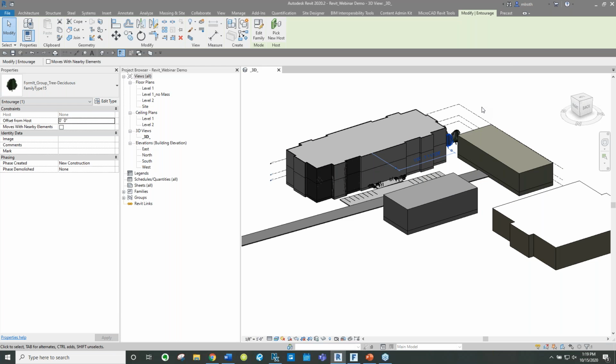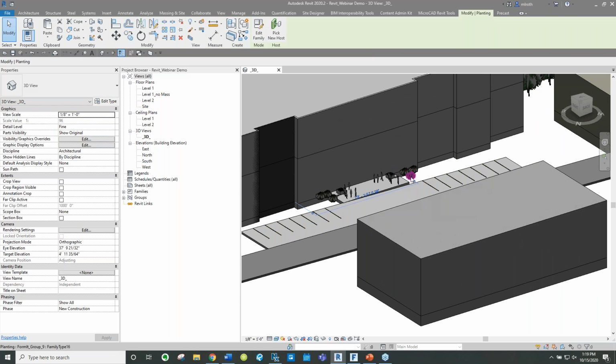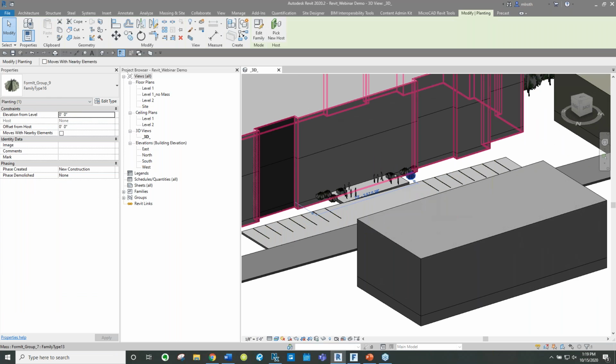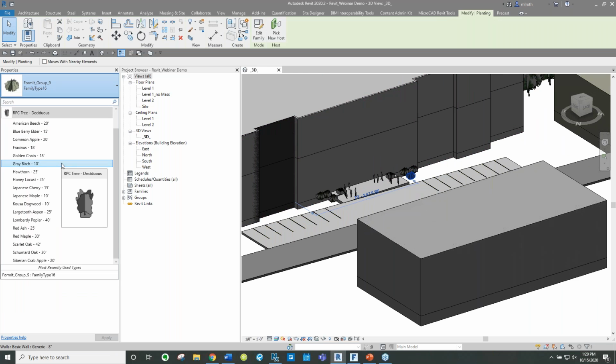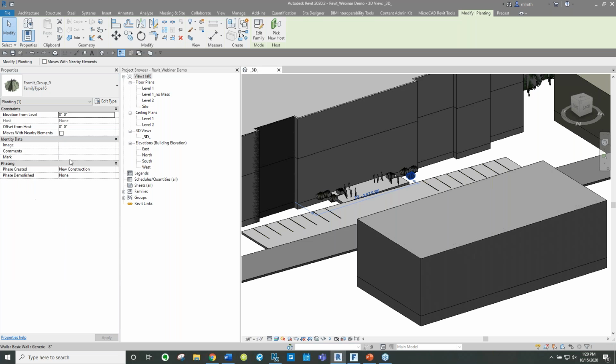If you are proficient or have the permissions within Revit, and specifically for your team, make sure your project managers are okay with this, you can certainly edit this family and change its category to something such as planting, which I have done with shrubs. And then from there, you can go in and start to swap out for any other information applied to that category within Revit.